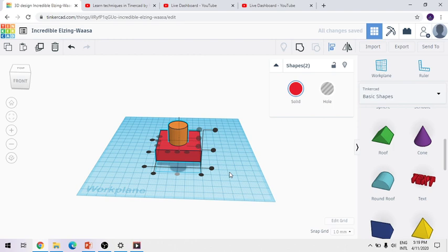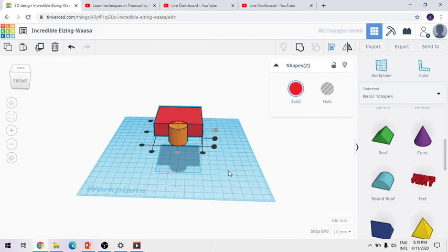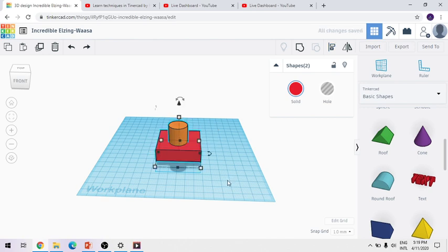Okay, then if I use this point, it is showing that the object will move to some other space if I press on this red point. Okay, then this is the z axis. So if you want to move your object in the upward direction on the z axis and I press like this, then the object will move like this. So this is called alignment. This alignment tool is used in most design techniques.